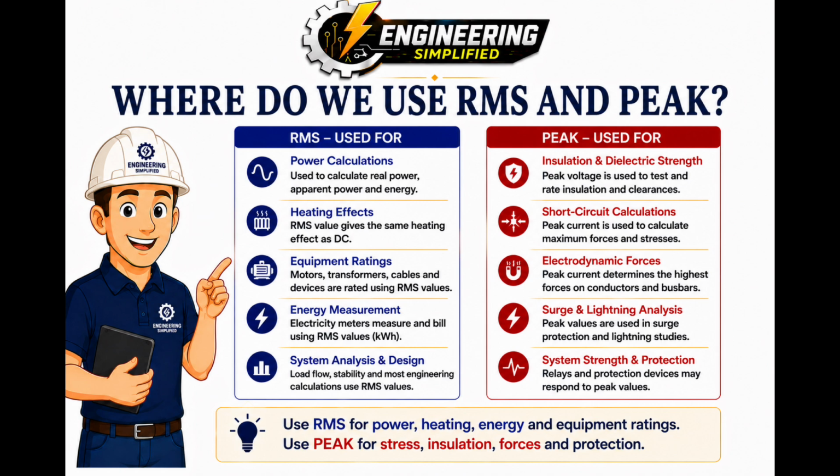Peak values become particularly important when considering insulation requirements, electrical stress, surge conditions, and short circuit forces. During a severe short circuit, the peak current can create enormous electrodynamic forces on cables, bus bars, and their supporting systems. This is why knowing whether a value is RMS or peak is so important.